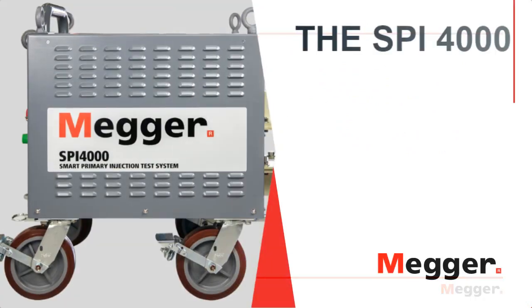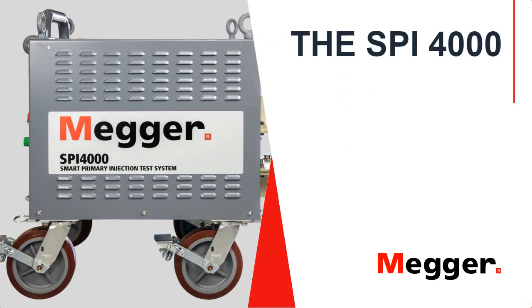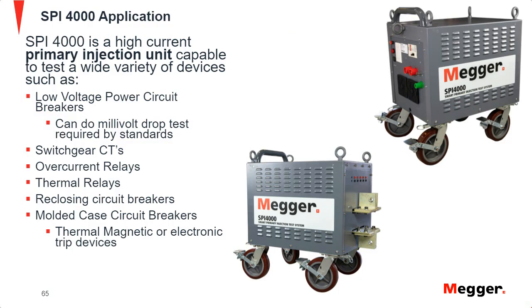With that being said, we're going to take a quick look at Megger's offering for primary injection testing. And this is our newest test set, the SPI 4000. This SPI 4000 is a high current primary injection test set, capable of testing low voltage breakers, switchgear, CTs, reclosing circuit breakers, and molded case circuit breakers.